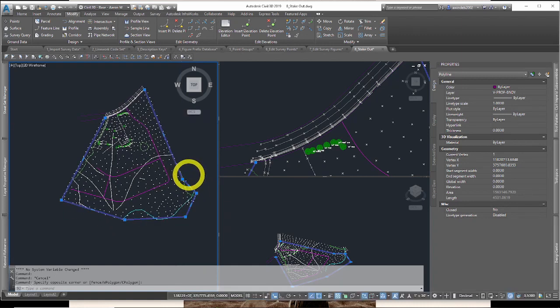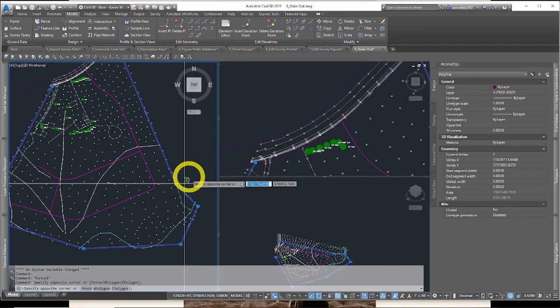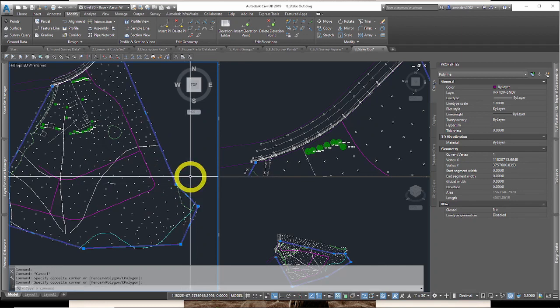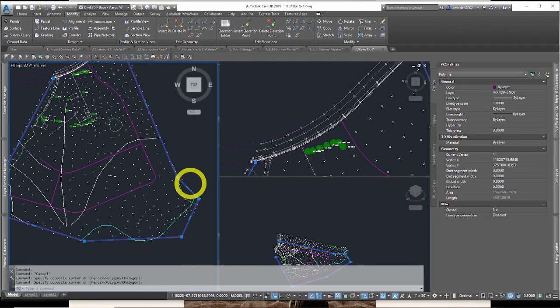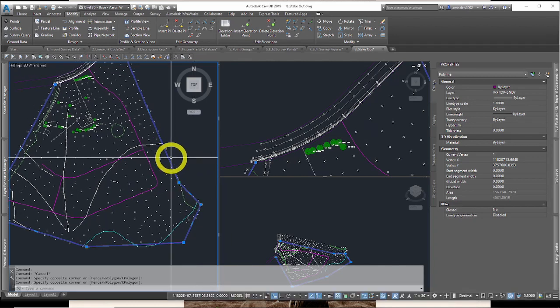You send a field surveyor or more into the field to find what monuments have been set, to later mesh in with what you drafted in your records, the monuments they found or didn't find in the field, to fit with your record as best you can. Maybe you hold the record better in other areas than some, but you take your drafting, your dry lab simulation, and then you verify it with your field data, which gives you your corrected final boundary in some respects, with a lot more that goes on in the background. But that's one reason you might create some points.